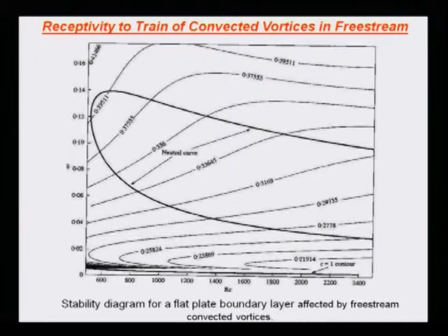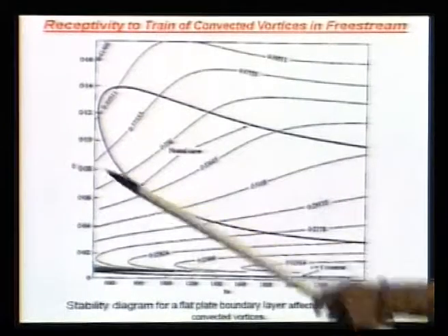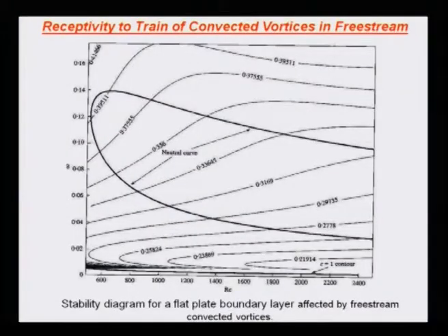That means the vortex is moving at a speed of u infinity, and that line corresponds to here in the Re-omega naught plane, and that is so far out of the neutral loop. So you would know it is very stable. So it plays little or no role at all in exciting a response field. Okay, so that is one thing.